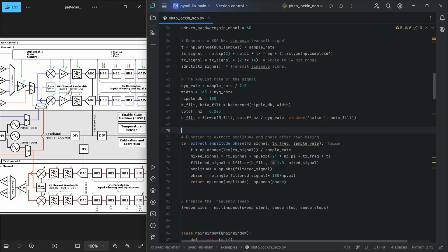We have a sine tone here, just fluctuating between +1 and -1. Because we don't have the exact definition of when we start reading back this sine tone, we can start reading from any point in this sine wave, right? So you are starting from an arbitrary phase in this sine wave, and this issue comes into the picture when we are measuring the phase.